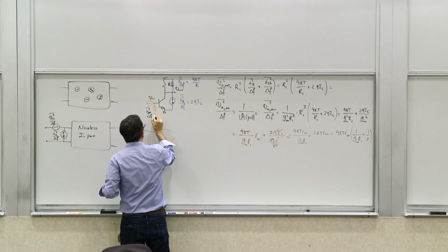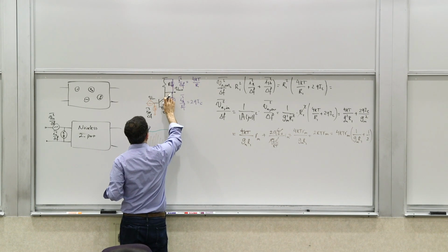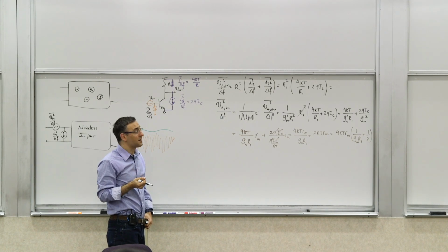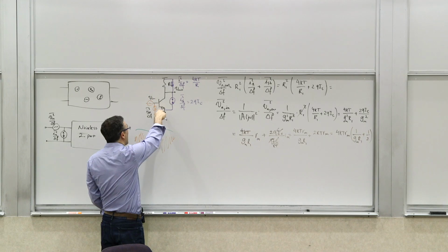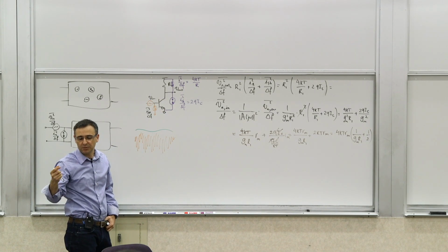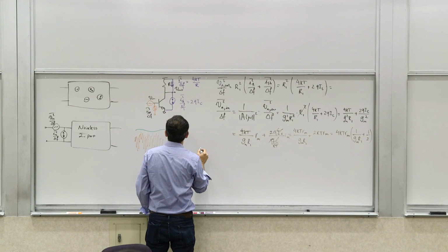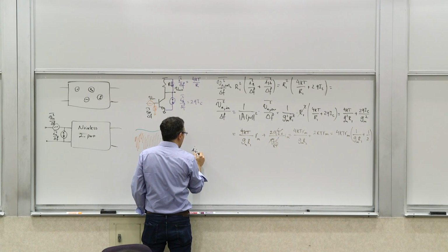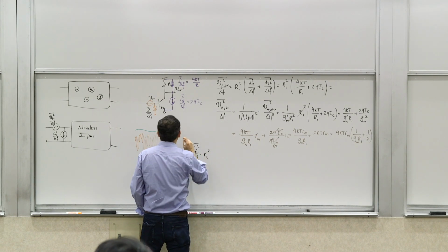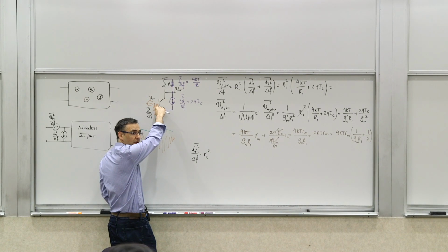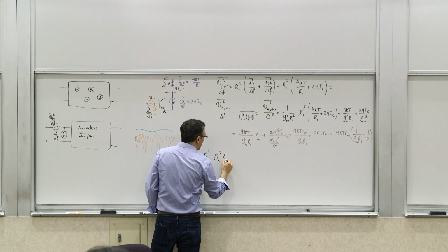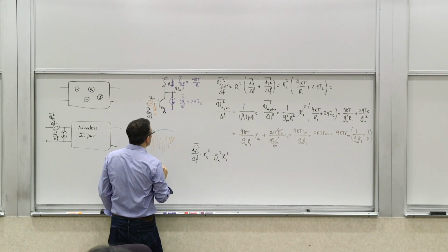squared over delta F. What is the transfer function from this I in squared to the V out? Well, there are different ways to think about it. One way is that this hits R pi, becomes V in, and that V in goes through the gain. It's a little bit of a longer path, but let's do it that way. So we know that I in squared over delta F times R pi squared is the voltage that this induces at the input. And this voltage goes through the voltage gain, which is Gm squared R1 squared, to produce the output voltage.